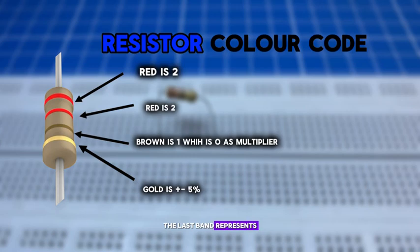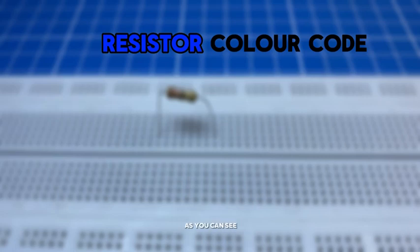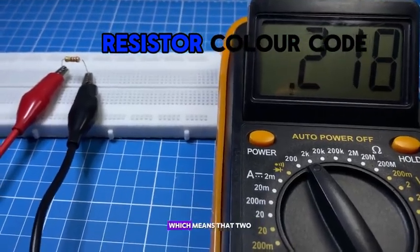The last band represents the tolerance level, and the tolerance level of the resistor is plus or minus 5% tolerance. So in this case, the resistance value of this resistor is 220 ohms, with plus or minus 5%, or 0.22 kilo ohms. As you can see on the multimeter, it is showing 218 ohms, which means that 2 ohms is the 5%.